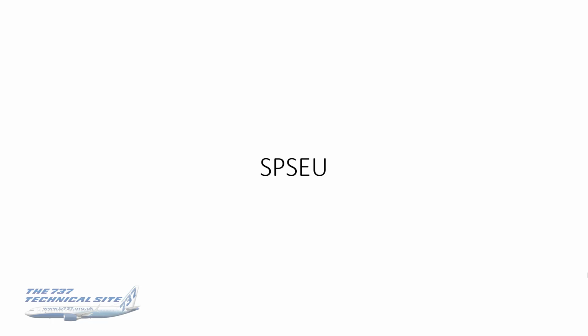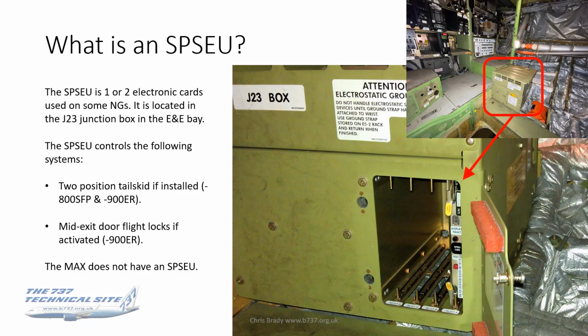Right, the SPSEU. What is it? Well, the name, it's a supplemental or supplementary PSEU. It's one or two electronic cards used on some NGs. It's located in the J23 junction box in the E&E bay, and it controls the following systems.